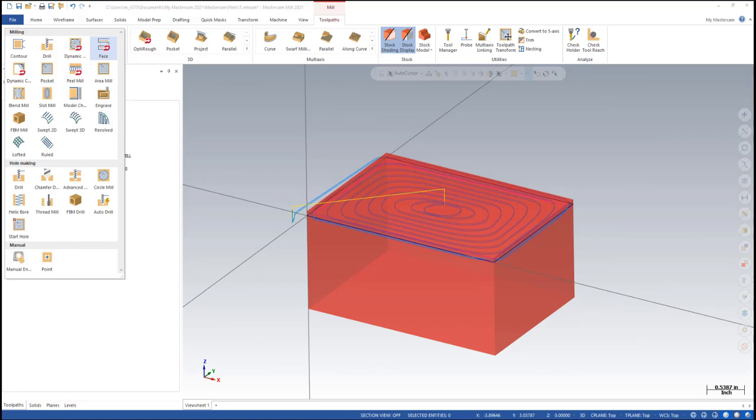When you first engage material, you're going to get a very large spike in radial engagement, and then it will stabilize throughout the cut to whatever you commanded it for your step over. And then as you come to the end, it's going to taper away, and you'll fall off to 0. So the dynamic motion just attempts to engage the tool one time, and then just keep it engaged as long as it can at the commanded radial engagement.